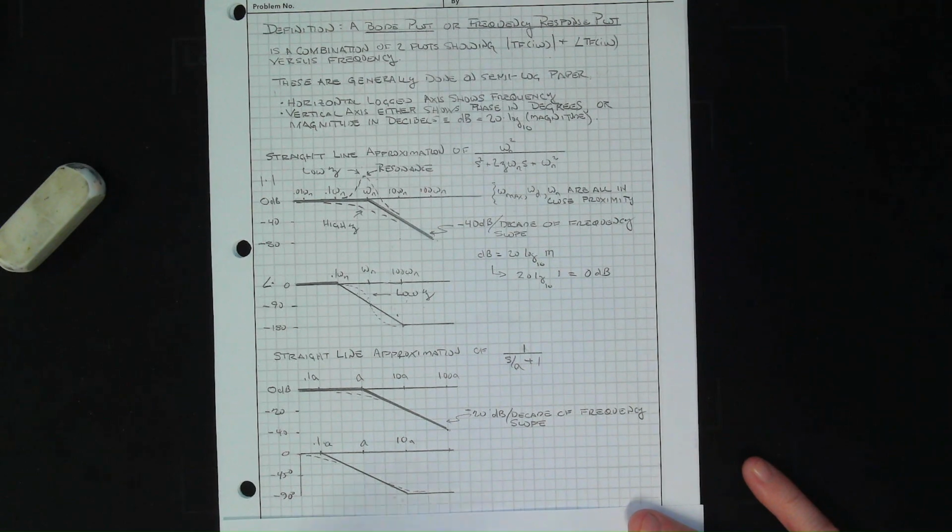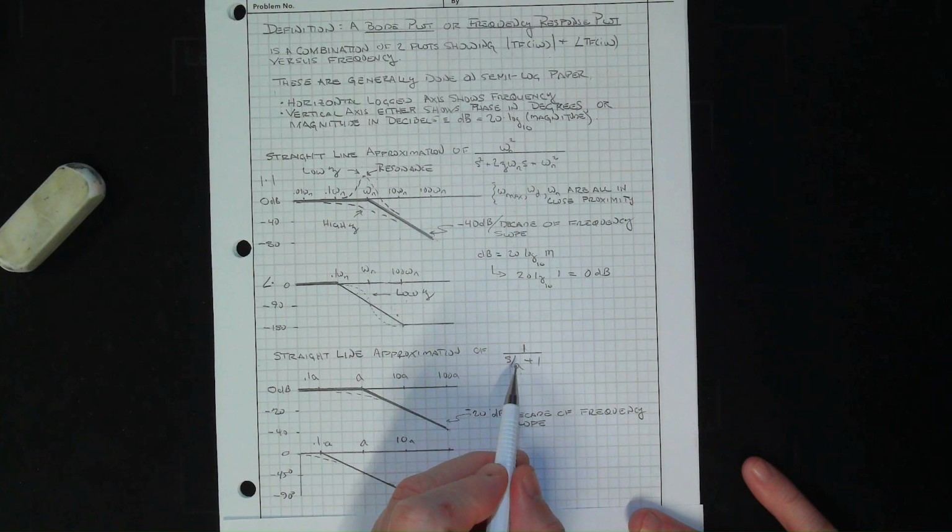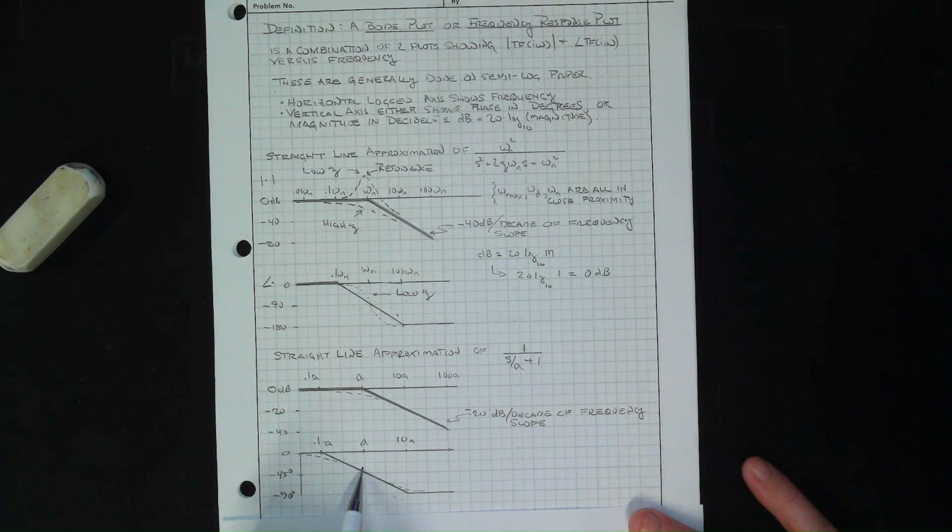All right, phase. It's kind of the same thing. Notice before we went to omega n, and we went 1/10 below and 10 times above, right? And at omega n, we lost half our phase. Well, at A, and notice this is where the root is, if you were to solve for this, you'd see s equals minus a. At A, we lose half our phase. So the straight line approximation says take this a, divide by 10, so it's 0.1a. So you start here, you go from 0, lose 45, and you lose the second half as you go up to 10a. And then it levels off at minus 90.